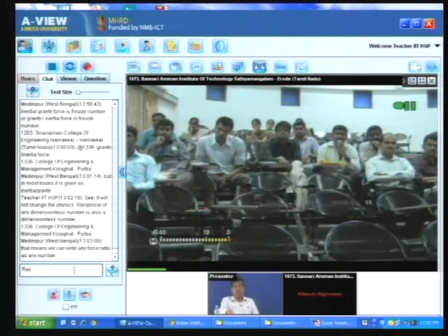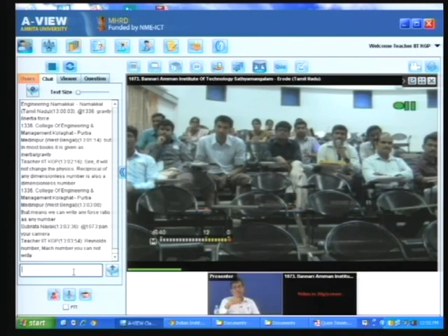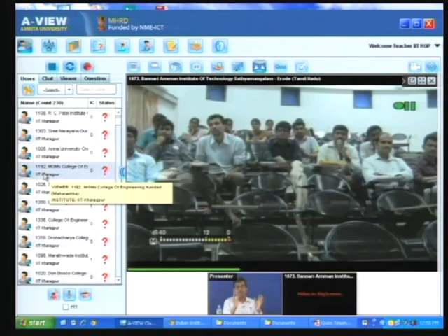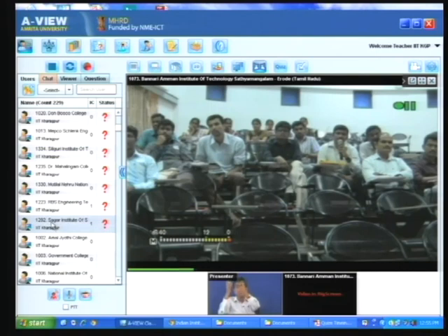So, you are predicting, for example, the pressure drop over an aerofoil in practice. You have to know what Reynolds number is encountered in practice, the range of Reynolds number. You have to do the experiments with that range of Reynolds number. So, your alteration of the physical variables must ensure that range of Reynolds number. You understand? So, that depends upon the problem. The actual problem in practice, you have to get the data. That is the data information, that is not your concept. You clear your concept first. So, what Reynolds number range you will use for the model experiments depends upon your data from the field. You understand me?